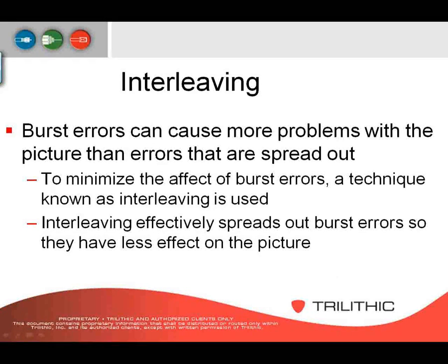Now, there is also what's called interleaving. A burst of errors can cause more problems with the pictures than errors that are spread out. To minimize the effect of burst errors, a technique known as interleaving is used. Interleaving effectively spreads out burst errors so that they have the least effect on the picture.